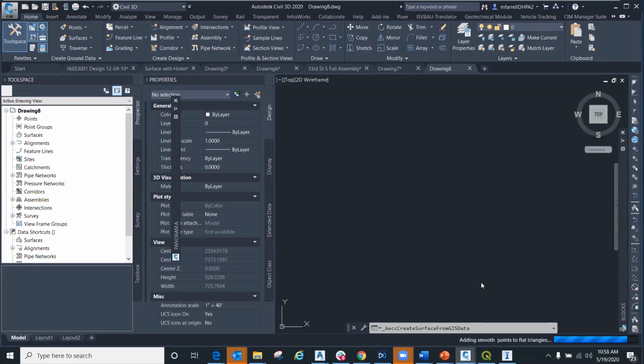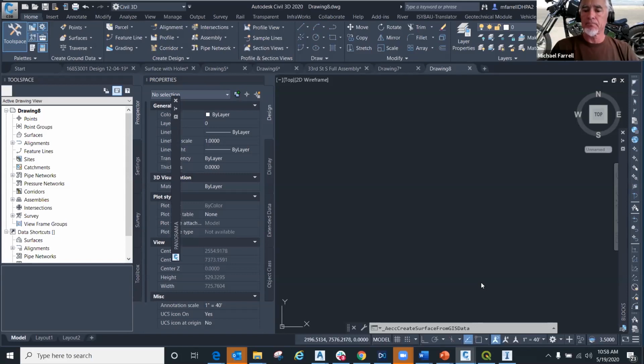I would use Civil 3D to make a shape file out of those contours first. Map export. Yep. And then once that's run, you can close the file and don't save it, because you have the shape file and all of the bits and pieces that go along with it: the projection file that knows which coordinate system it belongs in. You'll have all those pieces.